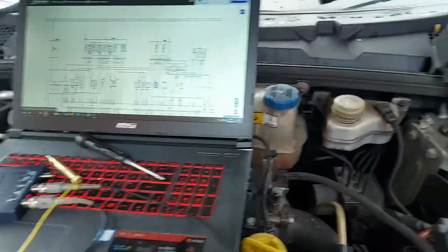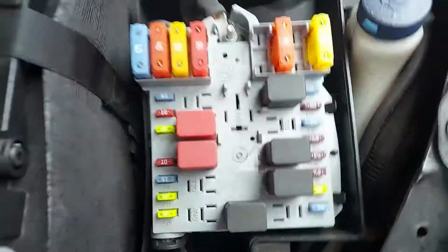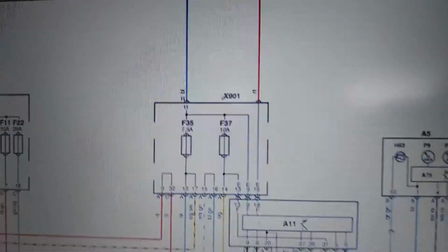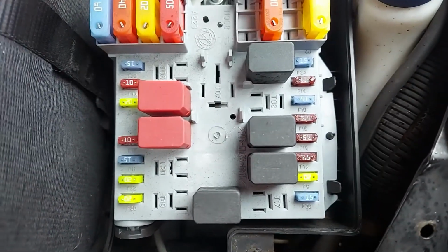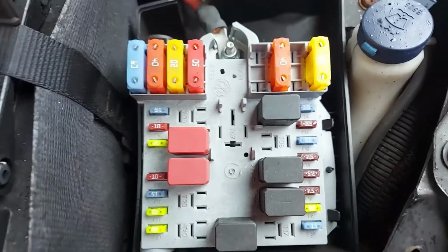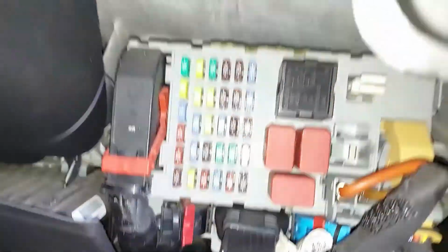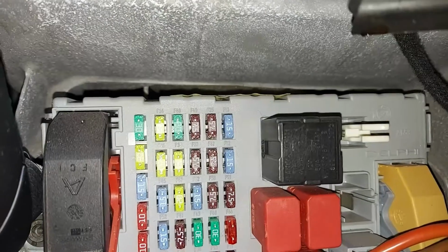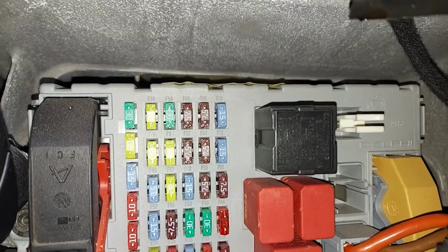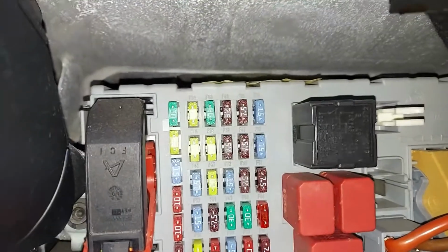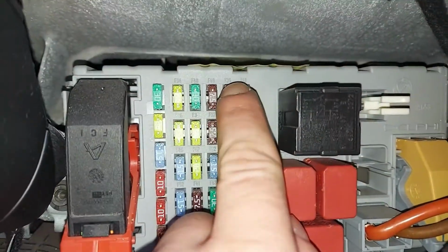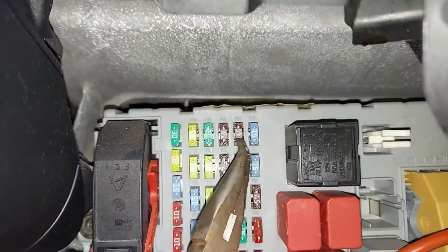Right. So here's a fuse panel here. I'm looking for fuse F35, if this is accurate. F30. I only get up to F30, so it must be a fuse panel inside the car then. Right, let's go inside the car. Okay, so the fuse panel is just above the OBD port. Let's see, I can't see anything. Put some light on. F44, F40. Oh, this is not even in order. Anyway, let's take it. Oh, there you go. F35. This one right here.